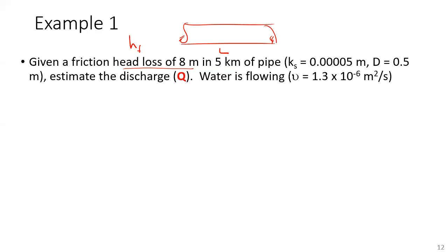What would be much cheaper? Measuring the pressure at 2 different locations, just like you did in Fluids Lab. And then you can estimate the discharge. It's a lot cheaper. So this is actually a real problem, and distribution networks and other pressure piping systems will use pressure drop, just like you did in lab, to estimate discharge.